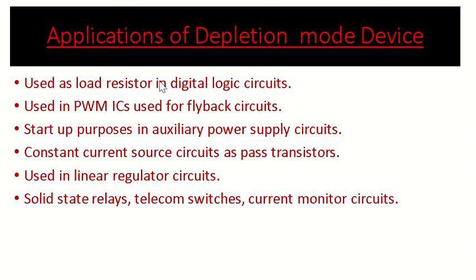We cannot operate MOSFET in depletion mode, because its construction is like that. For JFET, the construction is such that there will be a permanent channel between the source and drain, so it will normally be in the on state. No application of gate voltage is going to be required. So that is the main reason. Depletion mode usually means a JFET.